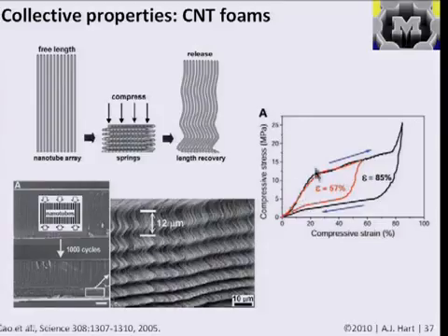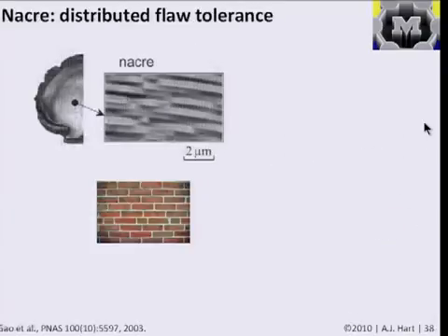And based on the buckling, you see this is classic foam-like behavior. You see ripples every time one of these buckles generates, and then when you unload it, there's basically a big empty space here, which is a lot of energy absorption. And so this is another possibility that has been used. So basically taking advantage of the individual nanotubes' characteristics of being able to kink and unkink, and collectively combining them into this foam that, if you looked at the modulus, it would be nowhere near the modulus of an individual tube, but this ability to elastically absorb a lot of energy, or maybe turn it around as an actuator or an impact absorber, could be quite interesting.